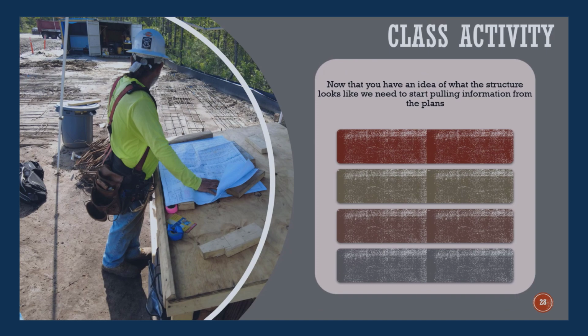Okay, excavation is underway. Before long, the team will be far enough ahead to start dropping rebar in the hole. If you were wondering when we should start tying the rebar, the answer is now. Let's write down some information our crew will need to add to our work plan. Before we start tying the rebar, we need to check the clearances of the rebar from the ground or from the form so we can find the dimension of the rebar cage.